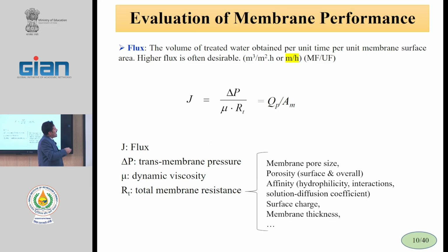And we now have the applied pressure. We know the viscosity of our solution, usually water, and we can calculate the resistance. With obtaining the membrane flux in the lab, applying pressure, and knowing the viscosity of the solution, we can calculate the membrane resistance. We know that the resistance of an ultrafiltration membrane is higher than microfiltration because it has a low pore size.